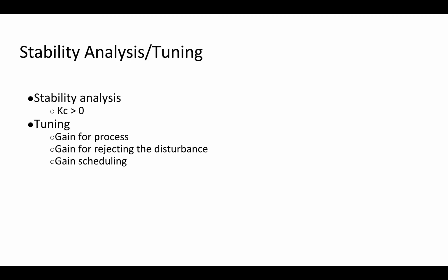We also worked on the tuning of our controller to tune the parameters, and that included gain scheduling for the feed-forward controller. The reason that we had to gain schedule the feed-forward controller is because the heat transfer of the windshield is a function of temperature gradient.